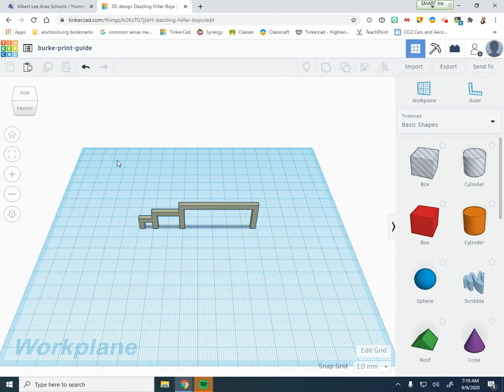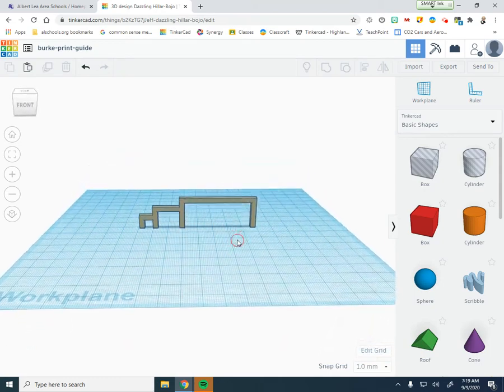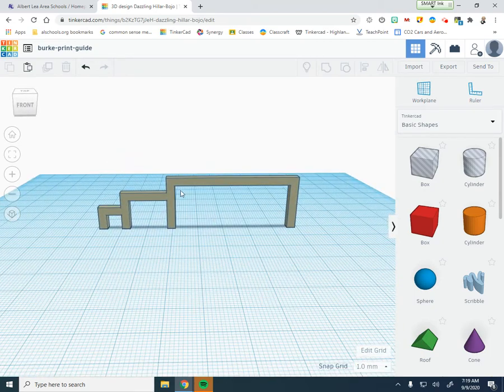We're going to put it up in the corner and kind of show what we're going to do with it. But one of the things we talked about when we print is if we were to print it like this and we printed our model, this gap here. Now this gap wouldn't be a problem now because we've scaled it down. But if we had this at the full gap width of 80 millimeters, our bridge would start to droop or have some filament because it doesn't have anything to hang on there.